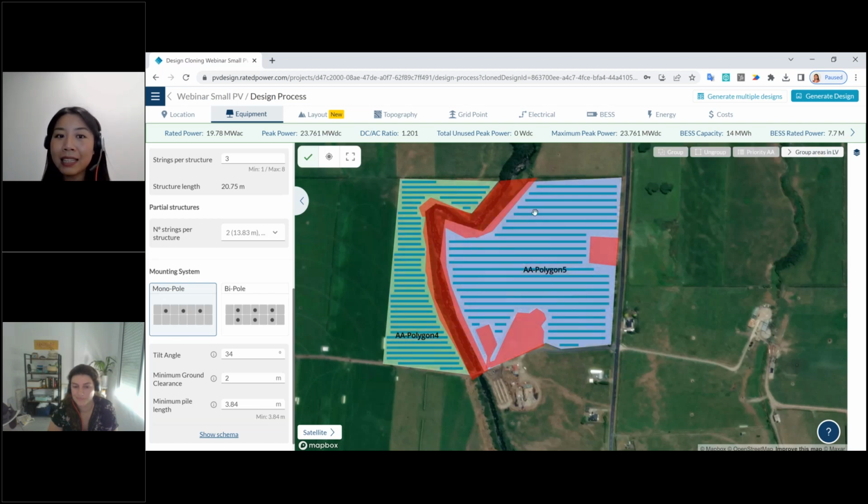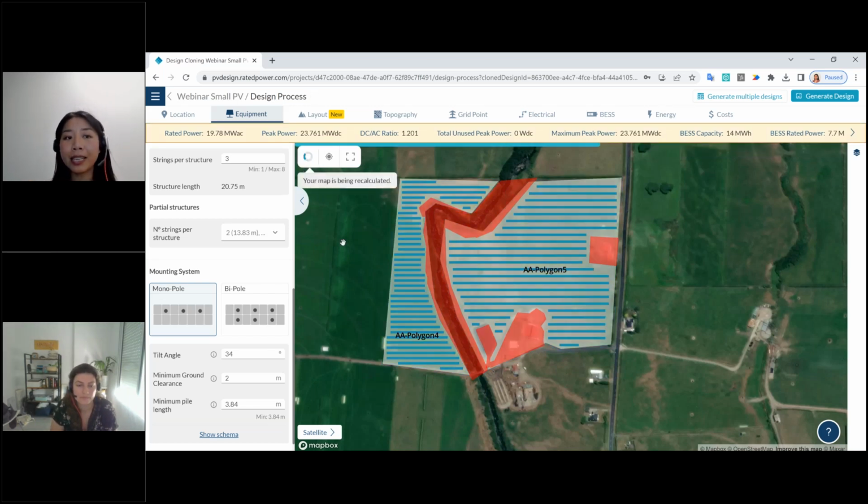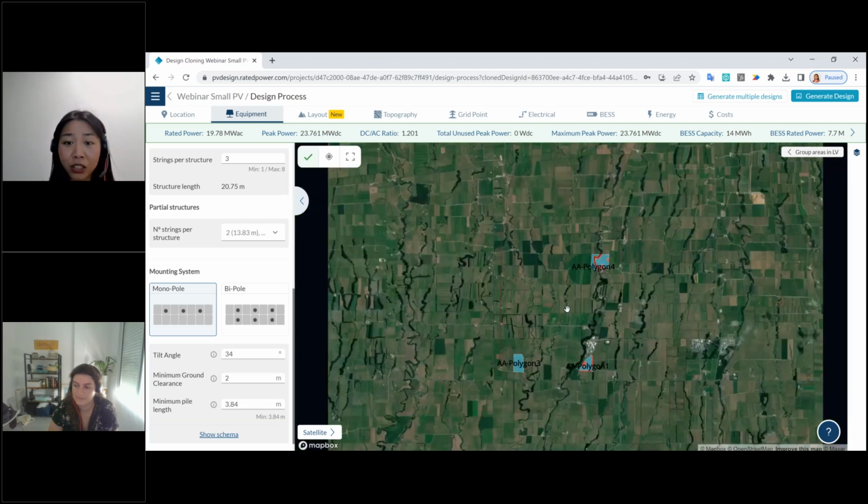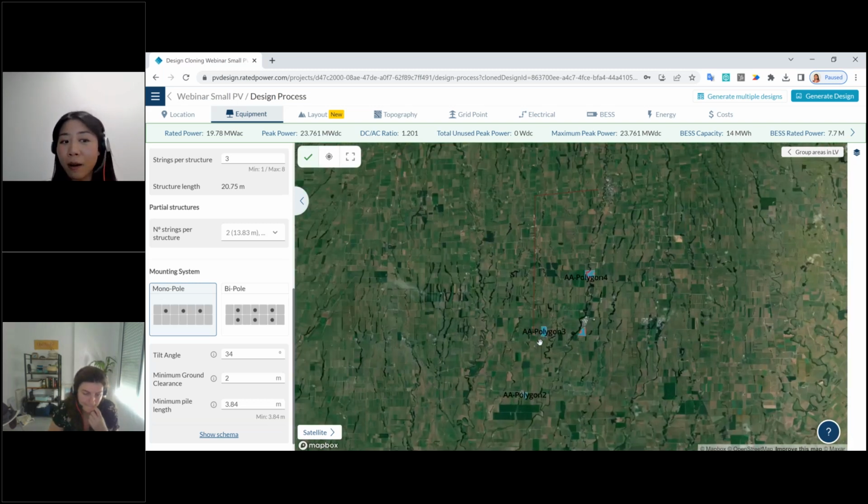system. Let's see these two areas that are actually adjacent to each other. Instead of connecting them on the medium voltage level, we can actually click on group to share the power station's capacity and share the low voltage system. And in the end, we can have a more optimized electrical configuration on this land. Once I have done that, of course, I can go into other sites also to adjust the most optimized parameters, but I will skip them.